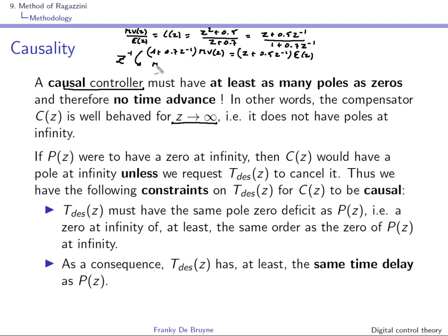We have MV at sample instant k plus 0.7 MV at k minus 1, so we take it to the other side, giving minus 0.7 MV at k minus 1, plus, and here's the problem, the error at sample instant k plus 1 plus 0.5 times the error at sample instant k minus 1.